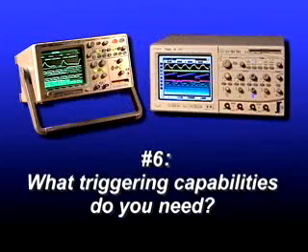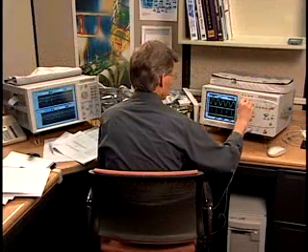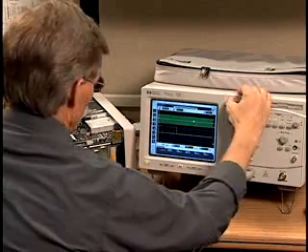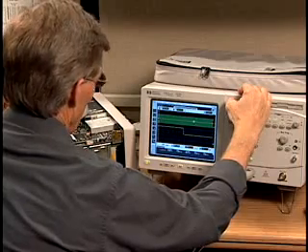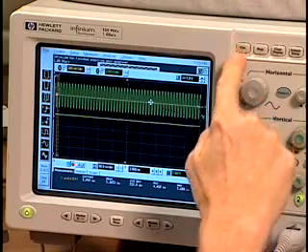Oscilloscope triggering essentially places the point of interest or concern at the center, left, or right side of the display for viewing. While many triggering capabilities are built into today's digitizing oscilloscopes, many general-purpose users get by using edge triggering when the use of more advanced triggering capabilities could save time and effort in viewing elusive events.